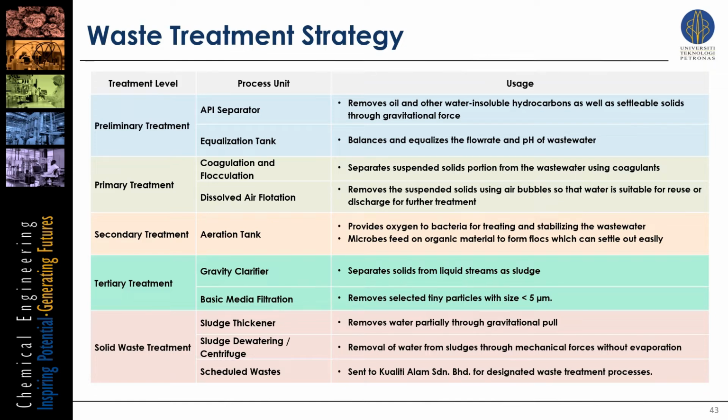system. In the coagulation tank, the chemical dosing will be added to cause smaller particles to accumulate into larger sized particles that are effectively removed through sedimentation. The effluent of coagulation and flocculation tank would then send to DAF unit. By using air bubbles, particles with lower densities compared to the liquid can be easily skimmed out as they float